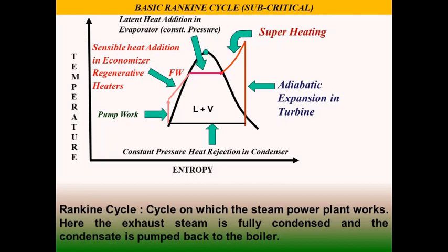There are low temperature superheating and high temperature superheating. Low temperature superheating is done in the primary superheating system. Primary is also distributed in primary LTSH in the second pass and platen superheaters. Subsequently, we have fine tuning and addition of more superheat in the final superheater, and it is sent back to the turbine for running the HP turbine.